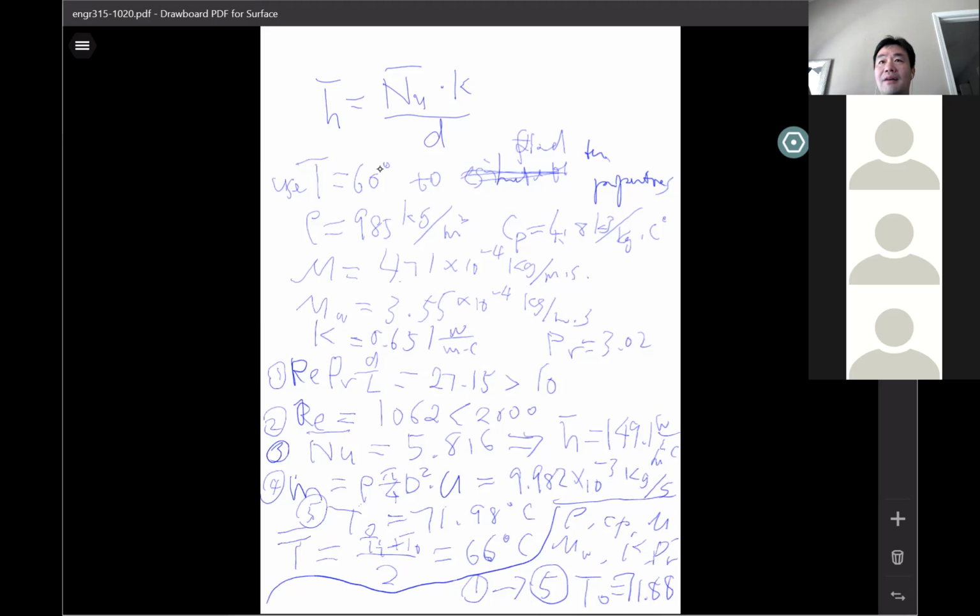You're an engineer, you want to have the most accurate calculation that you can. But you lack some of the conditions to do a best estimate at the beginning, because you should use the average of the inlet and outlet temperature to get the properties. That's the proper way. That's the average fluid temperature. You should use that, but you don't have it for this problem. The problem asks you to calculate the outlet temperature, so you don't have it. So what can you do?